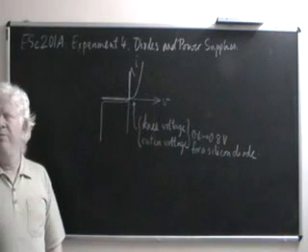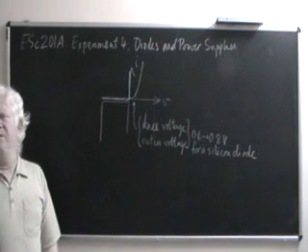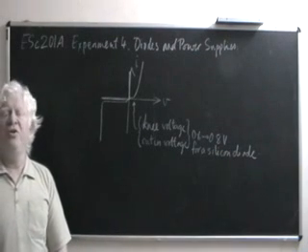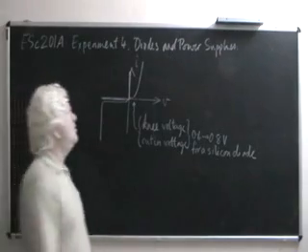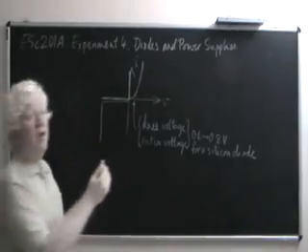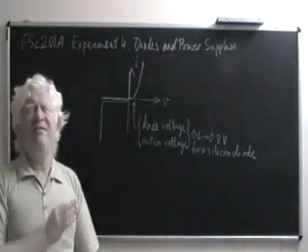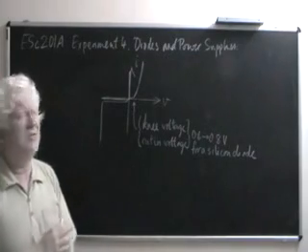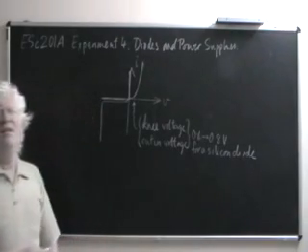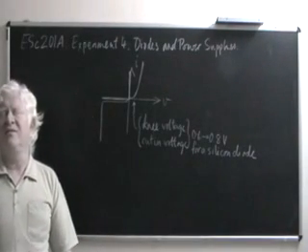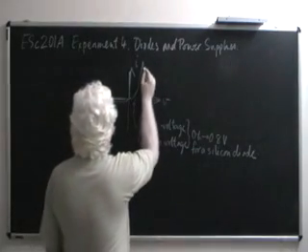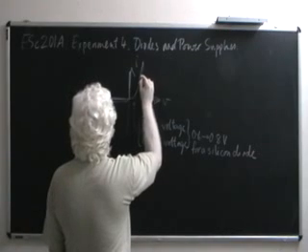Now, after it has cut in and after it starts conducting current, it still has a non-zero forward resistance, so that this part of the curve really doesn't have a vertical direction. It has a slightly slanted characteristic, as you can see, and this slant indicates that there is a very slight resistance, maybe of the order of a few ohms, and this slope, or rather the inverse of this slope,